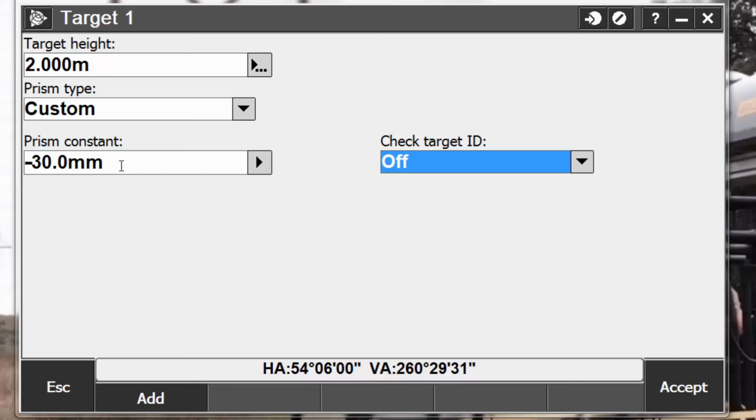For some non-Trimble instruments, the General Survey software will check to see if a prism constant has been applied by the instrument and the software. When you select Station Setup, the status line messages will show what has or has not been checked. If the General Survey software cannot check the setting on the conventional instrument, do one of the following.